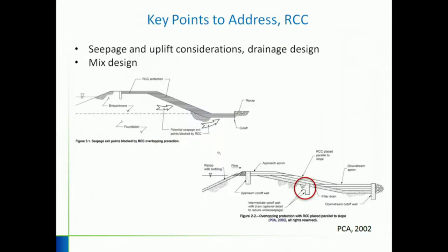So some key points to address with RCC. Since RCC is a strong material and also relatively impermeable relative to the shell material here, there are uplift considerations that we need to pay attention to. And seepage pattern changes when you place this RCC right here.